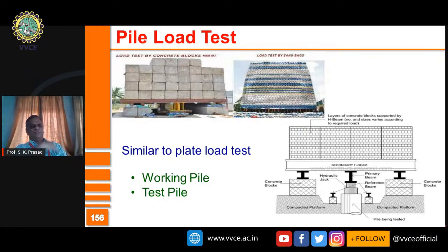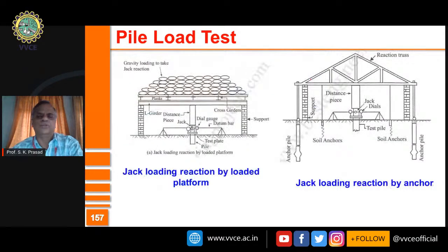settlement happens considerably. So what is done here, you either take the working pile, the pile which will be used later on for the construction, or you do that on a test pile which will be removed or replaced afterwards, or maybe which is just discarded as it is. And you have the pile here, you have a platform, and on the platform you're going to place heavy weights like concrete blocks or maybe sandbags, and keep on doing it till failure is reached.